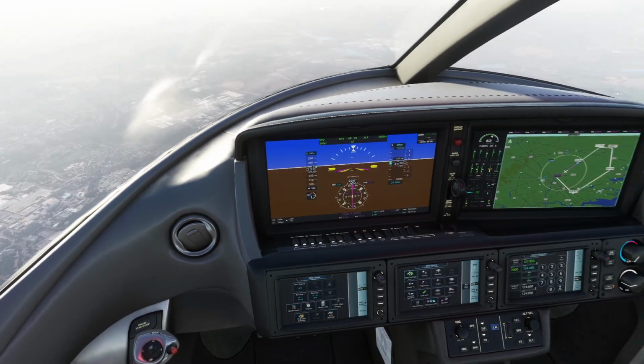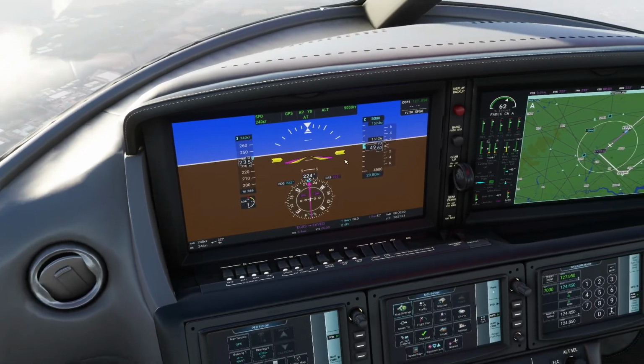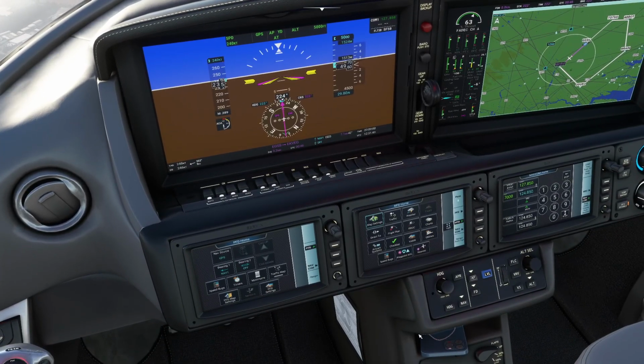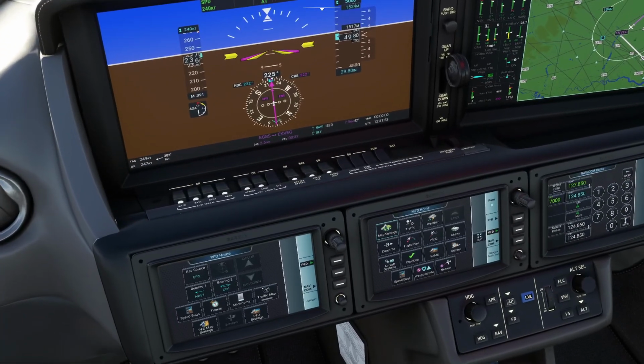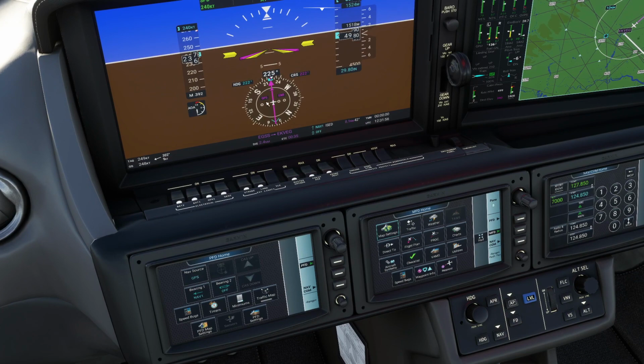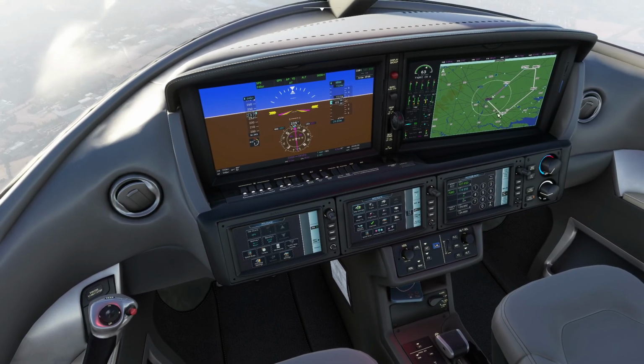Okay, so we've hit the target altitude. Look, the aircraft has switched over to altitude hold mode automatically. And that's indicated over here as well on the master control panel for the autopilot. It's still on nav mode, which means it's following the CDI mode, so GPS. So we're just coming up to Ekvej.